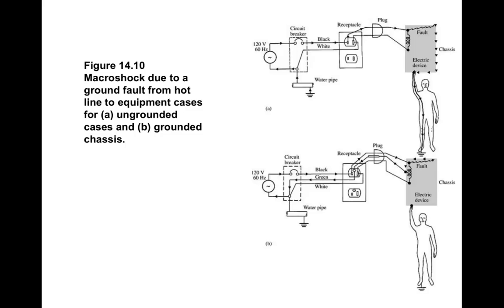So that's a problem because that means if you short out to your chassis, that's a problem. So here is the 3-wire circuit that has the hard ground. In this case, the hard ground or the green wire is actually connected to the chassis itself. So there's a direct short from the chassis to the building ground.